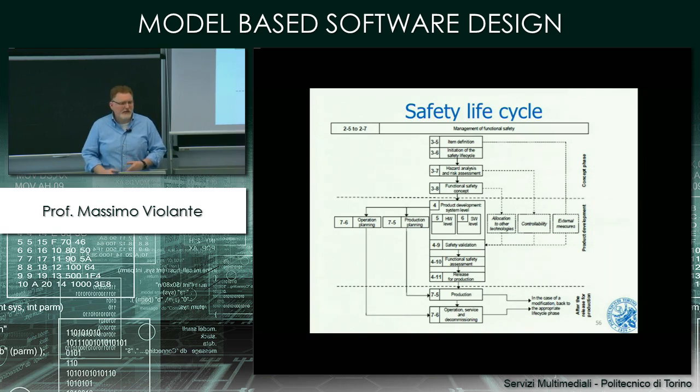The last stage is that when we have a failure on one of the sensors on the wheel, we give the driver the information: ABS not working, please be careful. This is the last resort. We can do nothing there. If the sensors that we need to operate are not there, we can do nothing. The only thing that we can do is to say to the driver, please be careful, ABS is not there to help you.